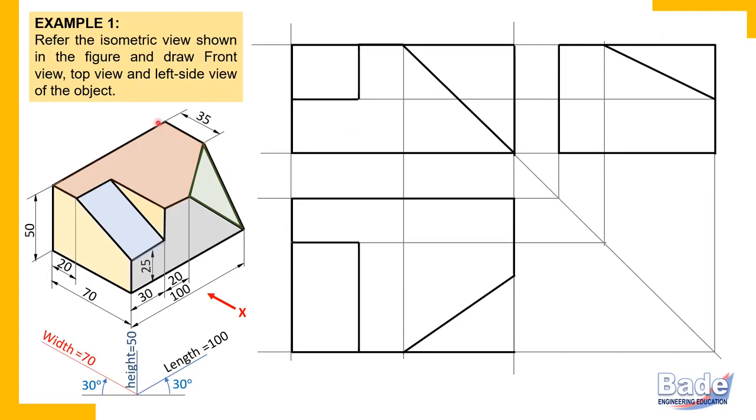But try to understand, this edge is already there in the top view, because this edge is the edge of this principal surface. So this edge parallel to width we have already drawn here. Watch here. So you may project this 35 millimeter distance from top view to side view, this way. So 35 millimeter, this length, check the end projectors here. Or you may measure independently 35.